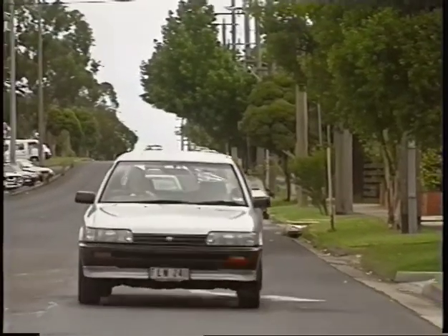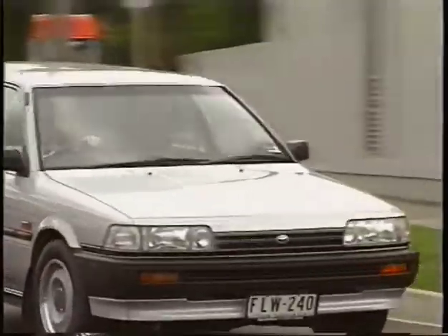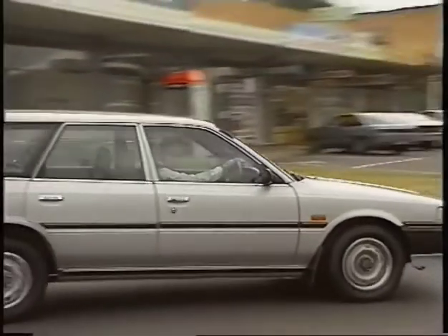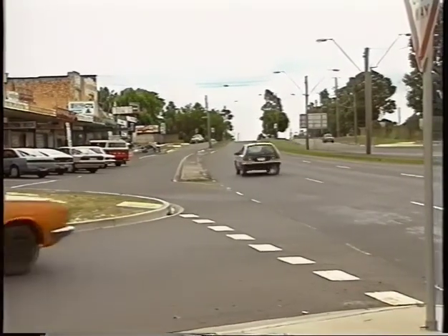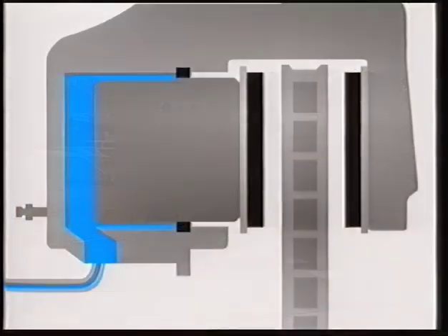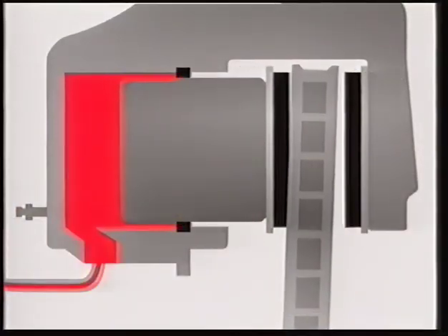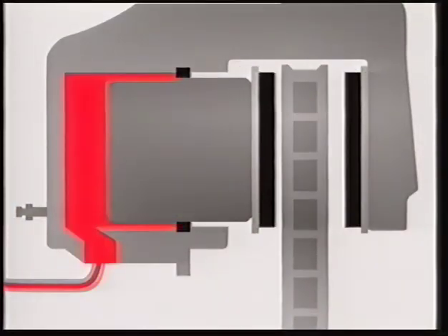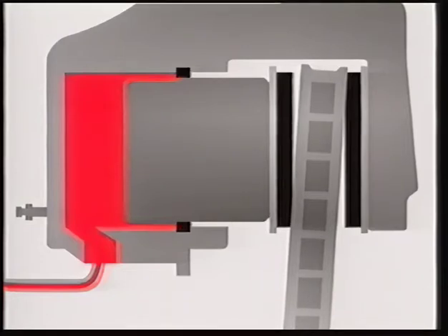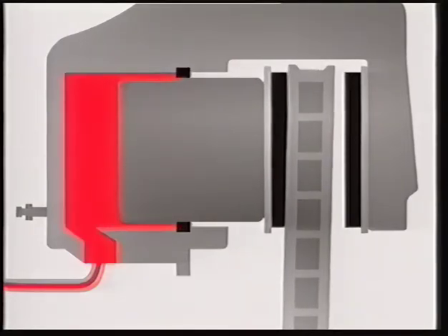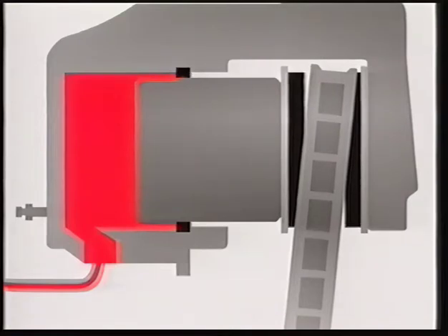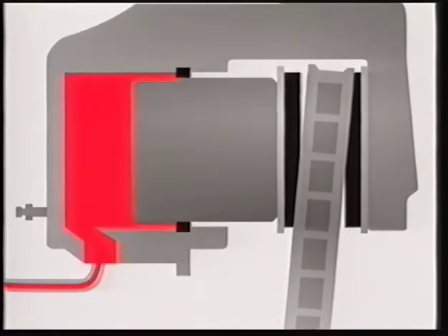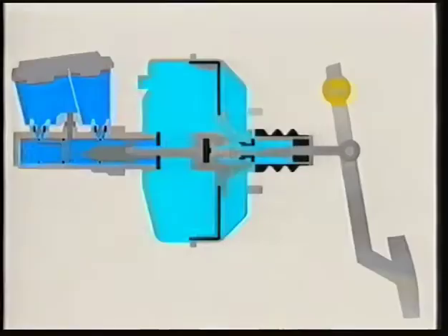Initially, this has little effect on the pedal height, but as the distance the vehicle travels goes up and consequently the number of brake applications increases, so does the pedal travel. In the case of the floating caliper, the piston applies the inner pad first, and then, because the caliper body can no longer slide, deflects the disc until it contacts the outer pad. Over time, the outer pad is worn down, causing the disc to be deflected further each time before it comes in contact with the outer pad.